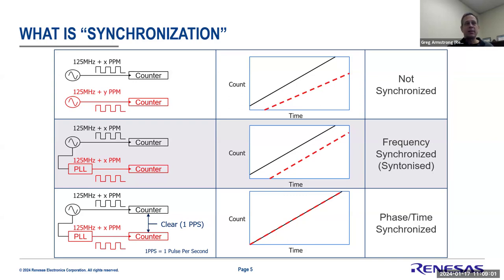But again, because there's no relationship of the counter, if you took a sample time and measured it in relationship to that clock, they would look like they're synchronous. But if you went over time and then started the measurement again, it comes back to which edge should I start measuring from? And so that's where phase synchronization comes in, and even time synchronization, where we actually try to have the events have a common relationship to a source.